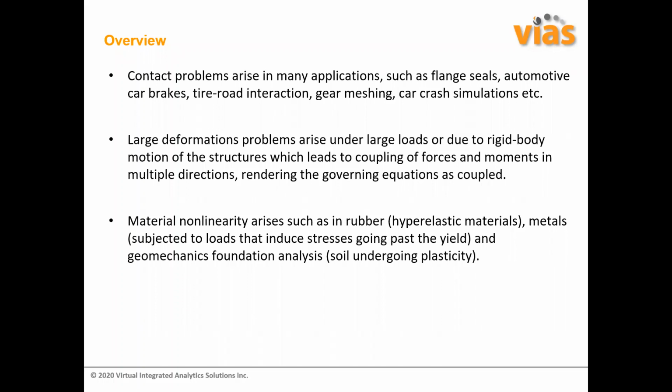Material nonlinearity arises because, for example, if you are dealing with rubber simulation or seal simulation, then you have a hyperelastic material, a very complex material, and the equation representation is very difficult, and it involves a nonlinear stress-strain relationship. Even metals such as steel, which is very commonly used in the oil and gas industry, may have complex stress-strain behavior, such as work hardening. And for geomechanics foundation, when we are talking about soil, it's even more complex.